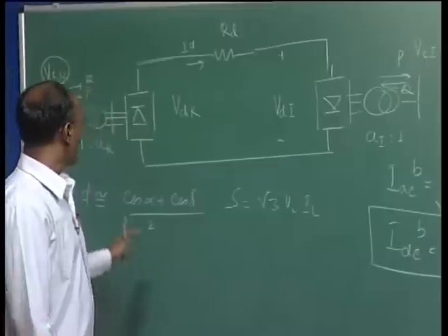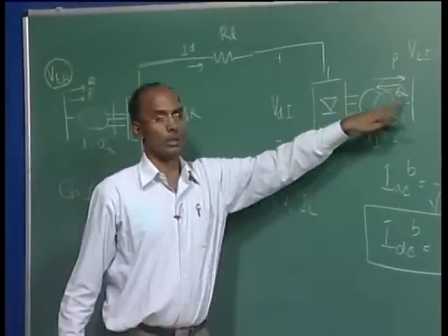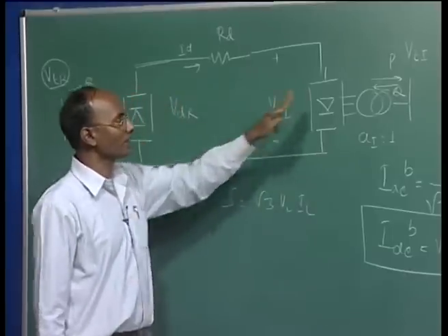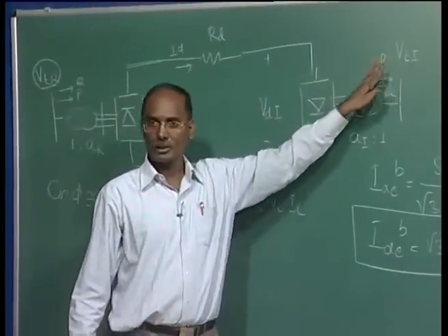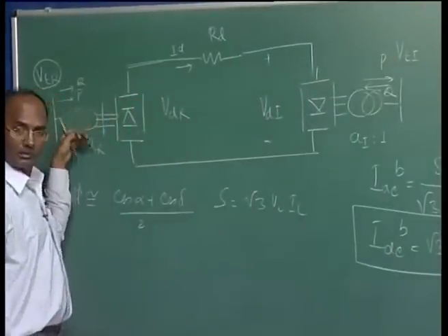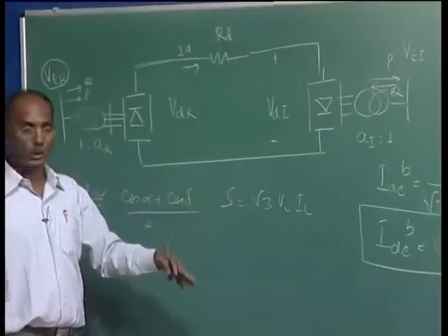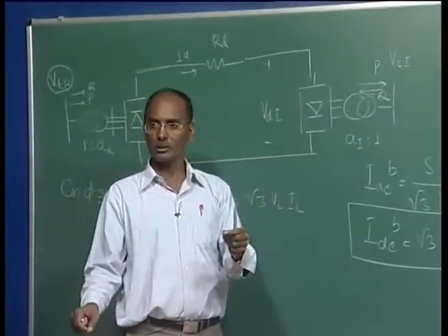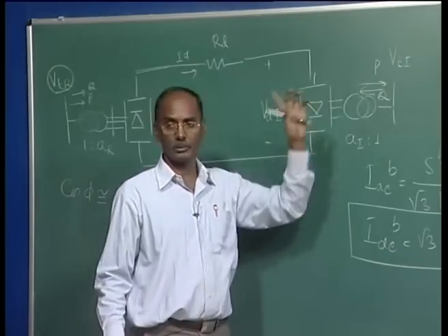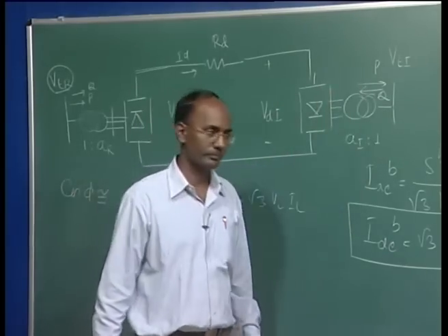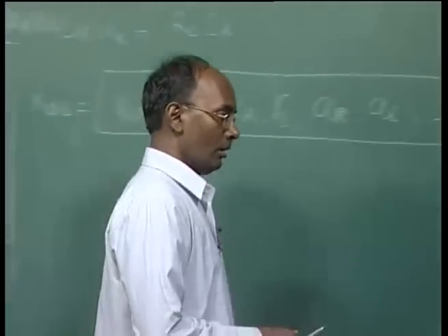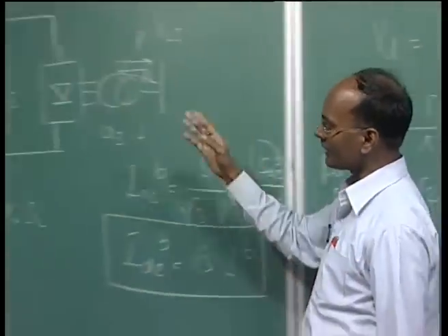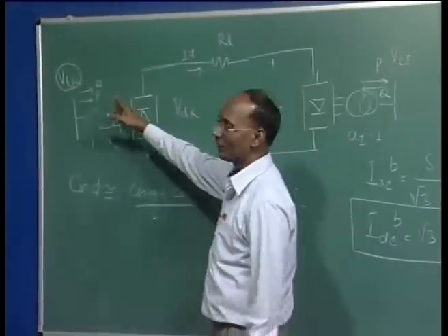By solving the DC network, we will get the P and Q here. Again the power factor here also means similar to this, only the direction of P is changed. Here you are taking as a PQ load, both are going away, means as a load. Here is a negative load. In fact, if load you are taking, the bus is coming out, you take load as positive, this is a negative P. Q will be in the same direction. This will be more clear when we combine the AC DC together, then certainly the P will be coming into the picture.